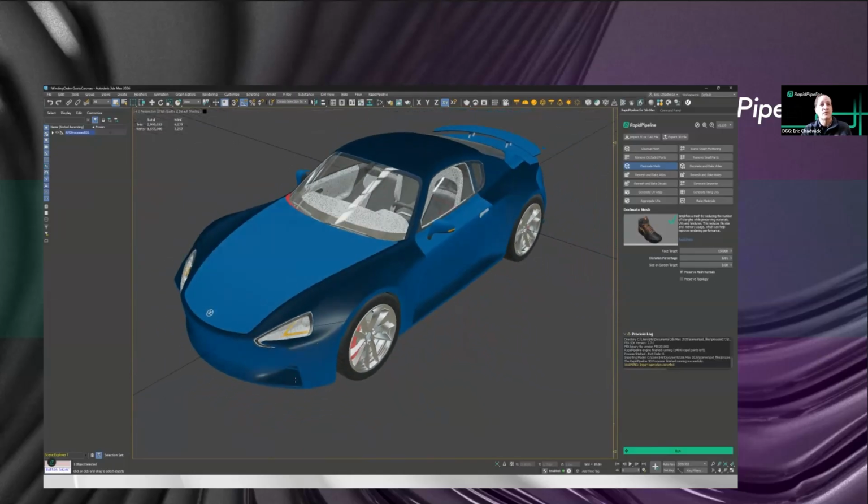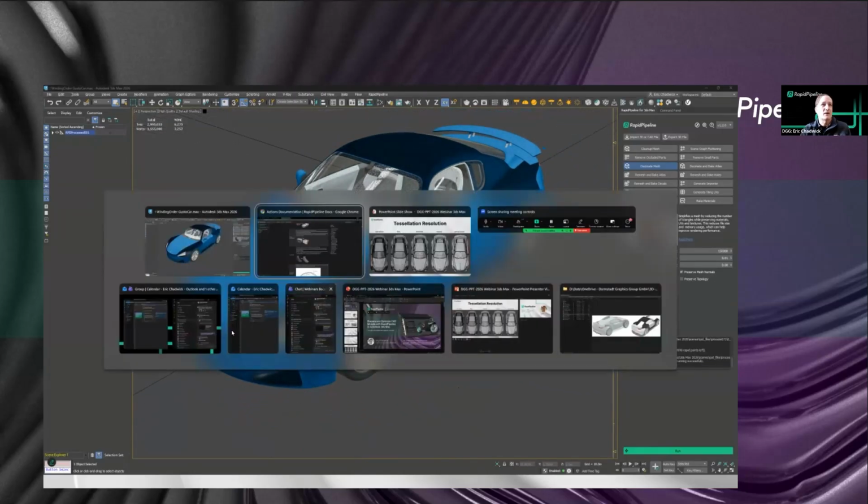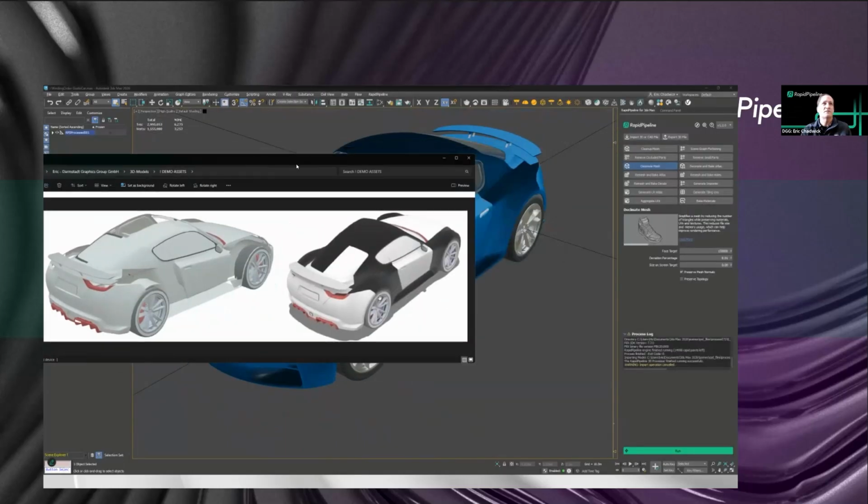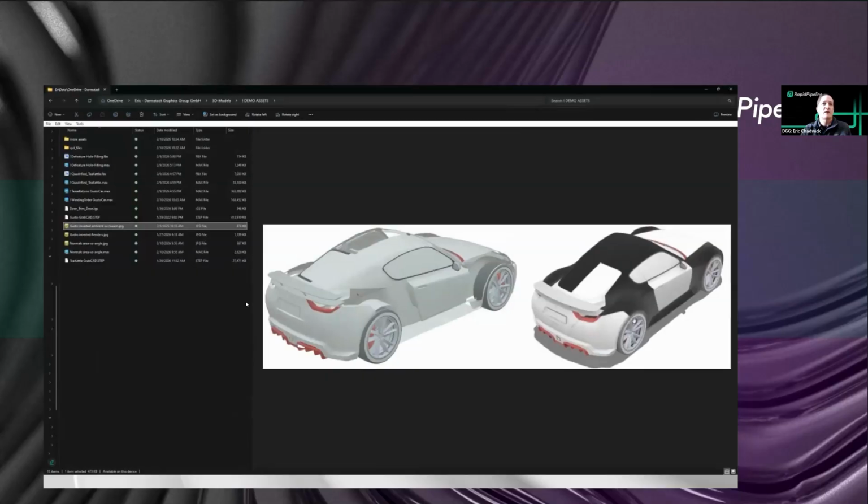And so that's going to cause various rendering issues. If we can look at an example here, I'll pull up another example. This is the viewport render with backface culling turned on, right? And those surfaces are inverted. If you go ahead and bake this surface and try to bake an ambient occlusion map, for example, or a normal map by decimating and creating a normal map, those surfaces that were inverted are going to render incorrectly.